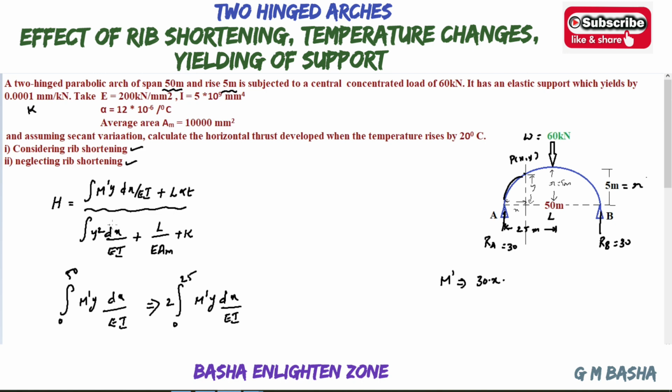And again, what is y equal to, for finding the intermediate value y between A and C? For parabolic arches, the formula is y = 4r by L square x into (L minus x). And what about EI? For EI also the values will be given. See here, the E value is 200 kilonewton per mm square and the I value is 5 into 10 to the power of 9 mm power 4.